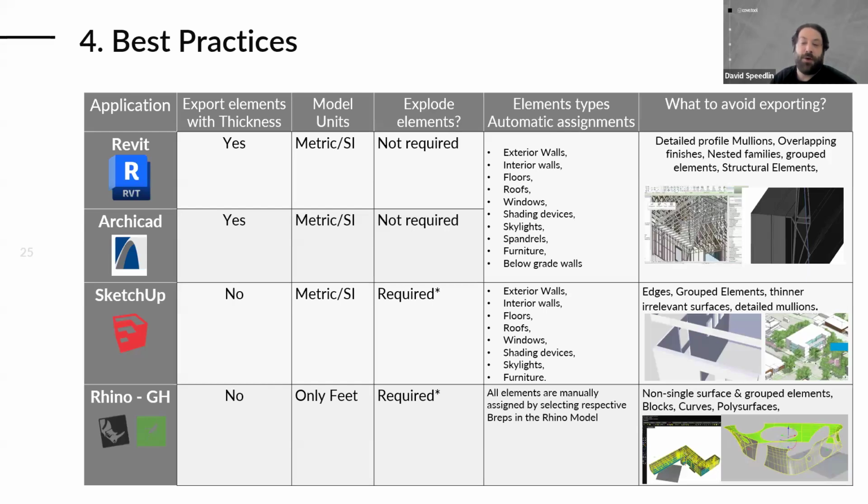Best practice right before you export again would be to select all the elements in the project, right click, hover over select, and click to deselect all the faces. That way you have all of your edges selected, and then you can set them all to untag before exporting. One good practice in Rhino is to make sure your final stage model is only single surface objects